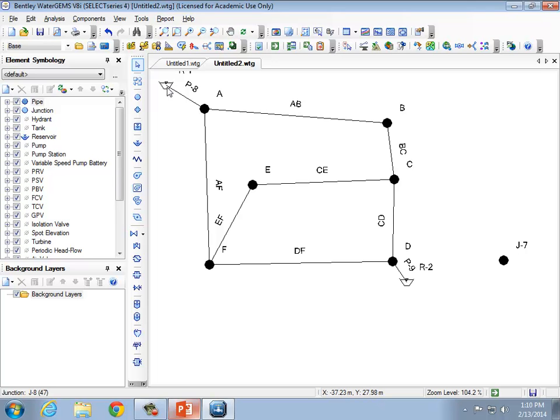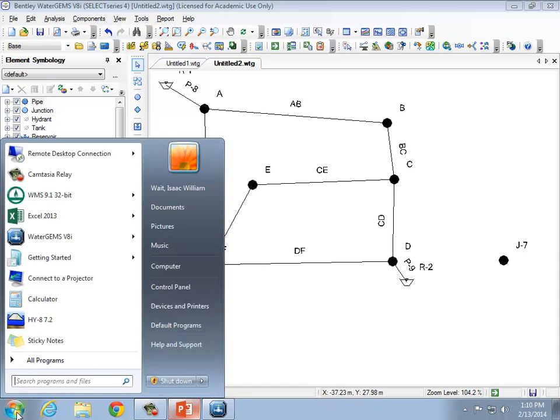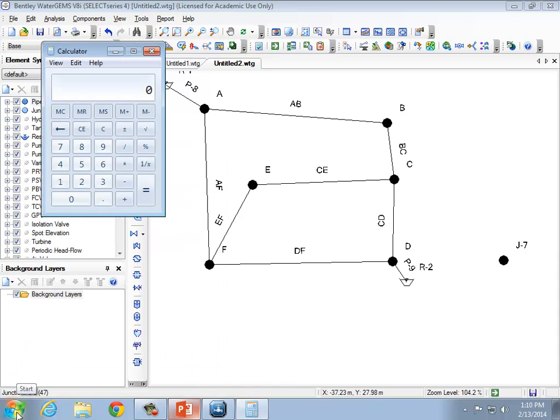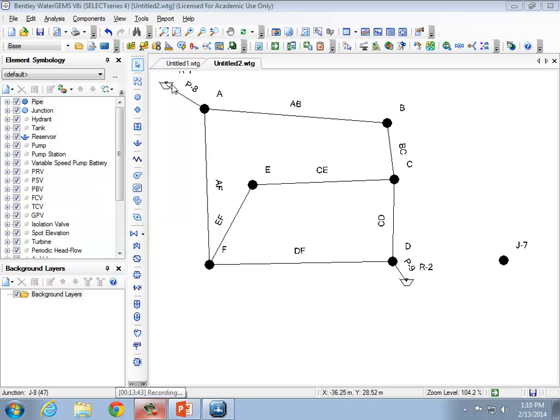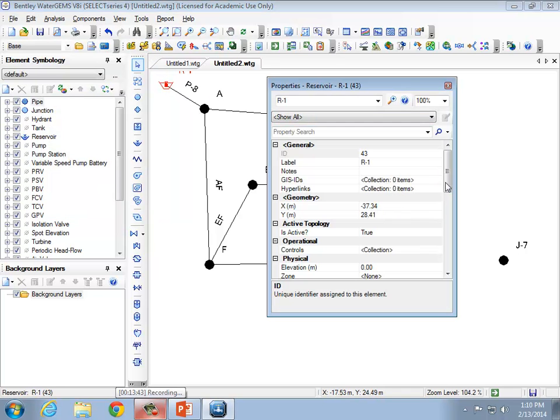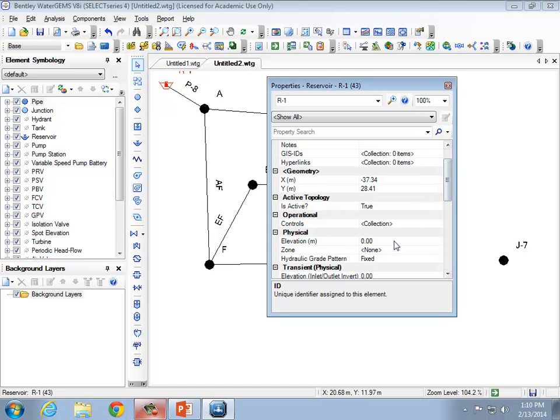And that tells me that the height of the water there, calculator, 600 divided by 9.81, 61.2 meters. So I'll do that, and then I'm going to check to make sure that I have the 600 kPa at A that we're expecting. So 61.2, right?